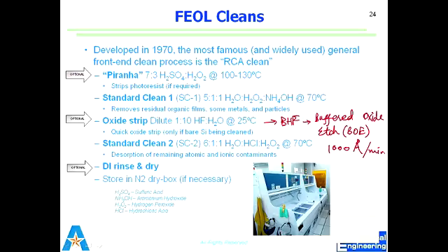A cascade is nothing but a container which has 3 pockets. We fill the top one with DI water, the water overflows to the next one, and that overflows to the next one. There's a continuous flow of water. So when I have my wafer, I need to rinse it. Should I start with the lowest one? I'd start with the lowest one and then go to the upper ones, because you're trying to successively clean the wafer in cleaner DI water, right? We'll talk about it.